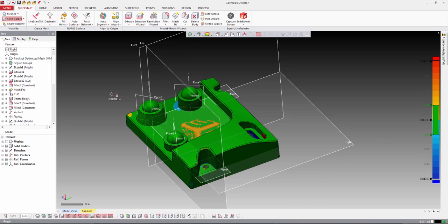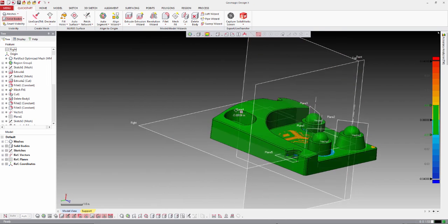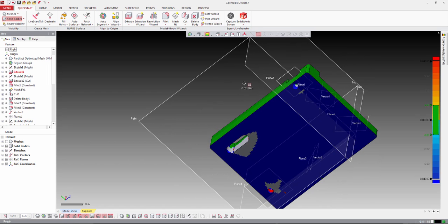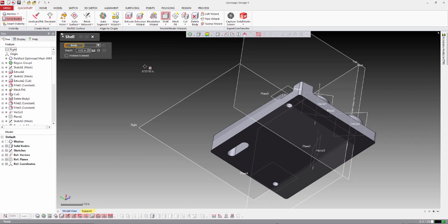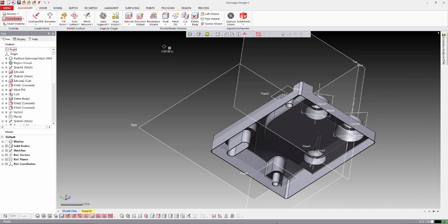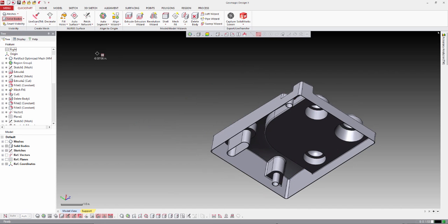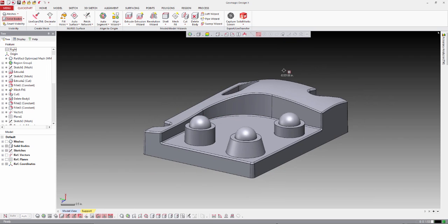The model is really quite accurate to the scan data. We've got the holes modeled in. We've got a lot of fillets and secondary features modeled in. We've taken care of all the draft. The bottom's not quite accurate. So if we wanted to do something like run a shell command on the entire body, we could do that, where we remove some of the faces. And running this command really shows that you're dealing with a true solid geometry here. So you're able to run a shell command and get this ready to go inside of your CAD system.